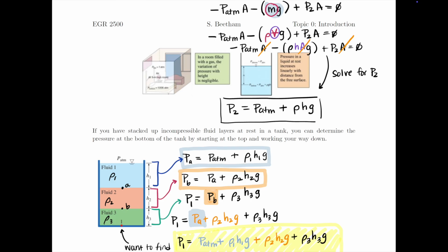All right, so I calculated what the pressure is in this tank using the height of that column of fluid, the density of the fluid, and the value of atmospheric pressure. Okay. Does this make sense, how the U-tube manometer is working? So just to recap, generally when you solve these problems, you want to find a line where you have points 1 and 2 and the pressures are equivalent. And then you can do a force balance at one of those points. In this example, it was point 2. Does that make sense? Questions on this one? Okay.